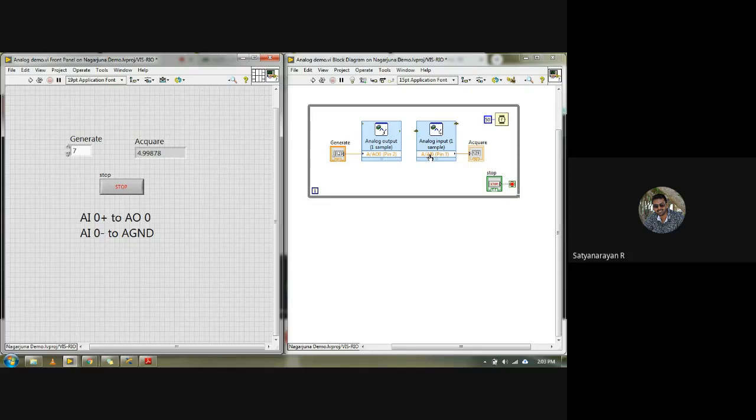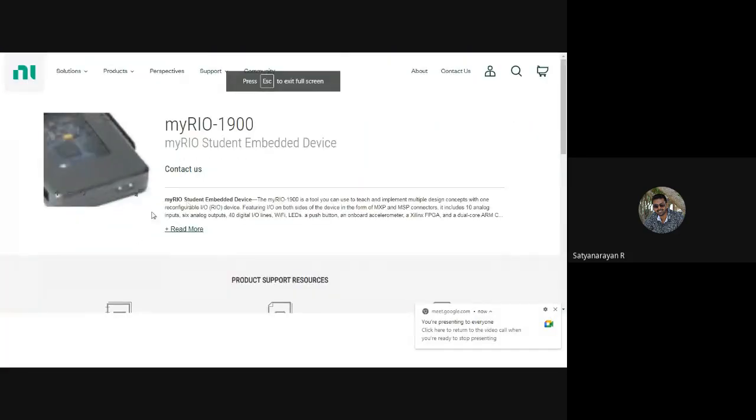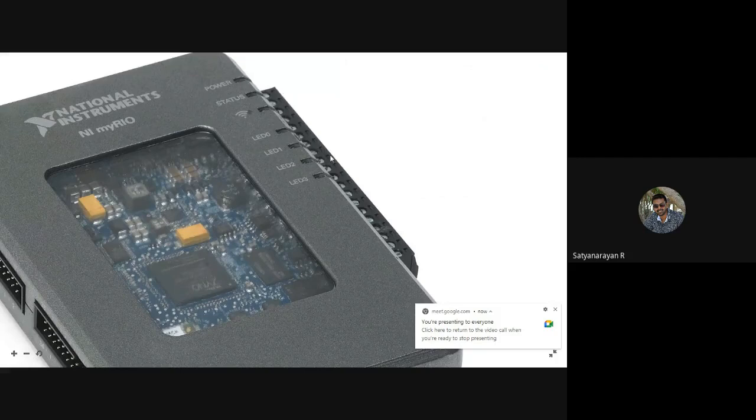Then if you come to the mini system port, MSP, you can use the connector block. A connector block, in the sense like I'll just show you. Here, if you see, I have a black port with all the tiny screws. This is what we call a mini system port, MSP. It is available similarly in our MyDAC. This is the female connector, so that we can take male pin connectors and connect through the wires.